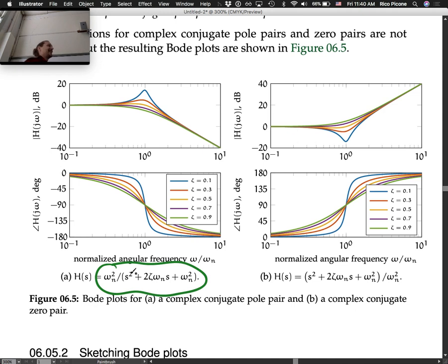Yeah, you separate it into two different functions because it's third order now, a first and a second. Yeah, so you could contrive to have an omega n squared in the numerator. So say you had 1. You could multiply it by omega n squared divided by omega n squared, but save the divided by omega n squared out front, and that becomes a constant transfer function by itself, right?